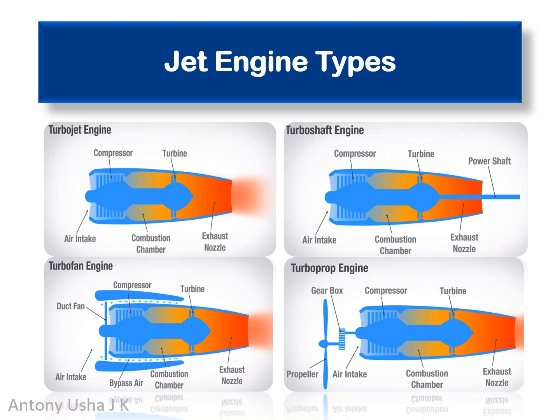In a turbofan, a large ducted fan at the front pulls in more air. A portion of this air enters the core, like in a turbojet, but most bypasses the core and is accelerated by the fan. This bypass air generates additional thrust, making turbofans more efficient and quieter than turbojets, especially at subsonic speeds.